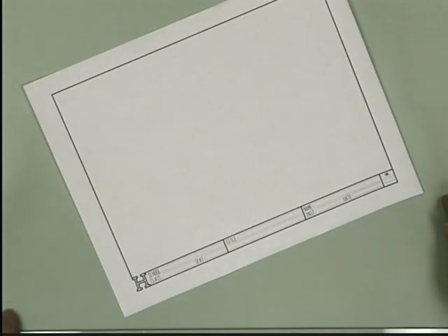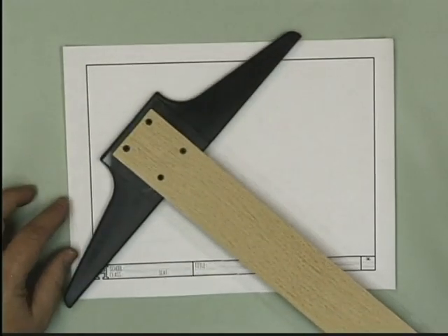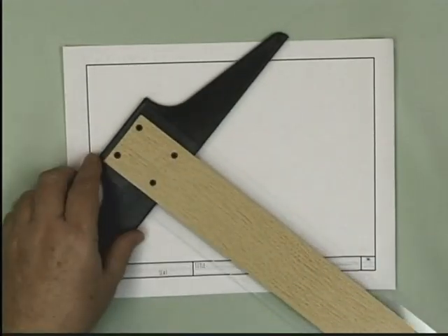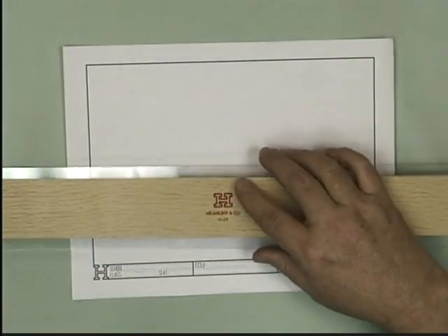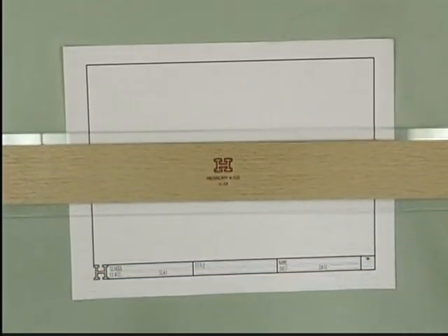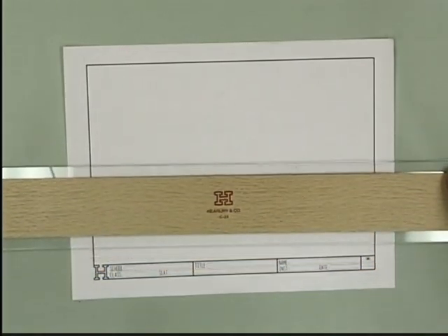Well, now that we've practiced making a few lines and we saw how to erase lines and use the dry cleaning pad to keep a drawing clean, now we're going to get a little more formal, and I'm going to take this pre-printed title block drawing form, and I'm going to tape it down to the drawing table. And I want to align it using the T-square. The T-square has this nice head and a very smooth straight edge, and just off camera when I slide this over, it's just going to slip over the edge of my drawing board, and then when I run it up and down, keeping the edge in contact with the side of the drawing board, I'll be able to make parallel horizontal lines.